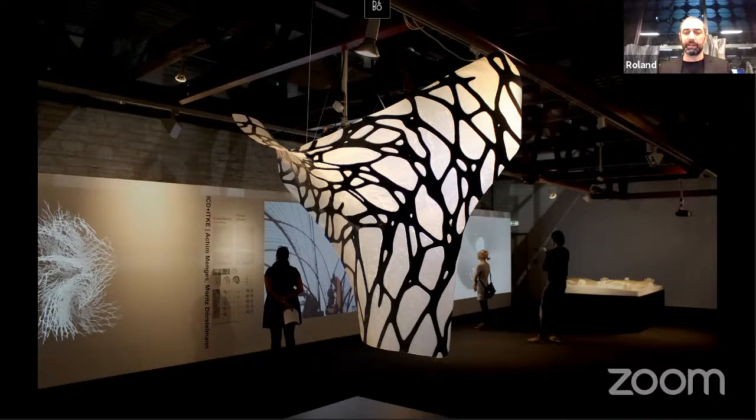Once the skeleton had found its form, we then infused a very, very thin layer of glass fiber on either side of that. So in the end, the glass fiber in this project is only 1/4 millimeter thick, but provides all the shear strength for it, while the carbon fiber skeleton provides the primary structure. And in many ways, this was a breakthrough in this quest to try and do without the mold in the work that we're doing. But it also had another problem. It made something which was very, very thin.